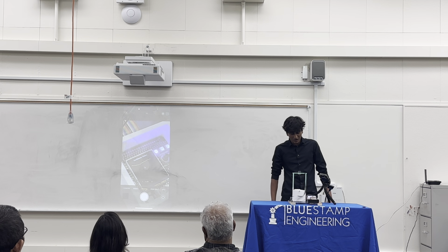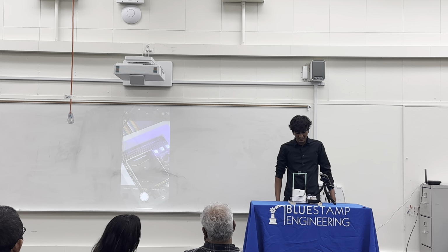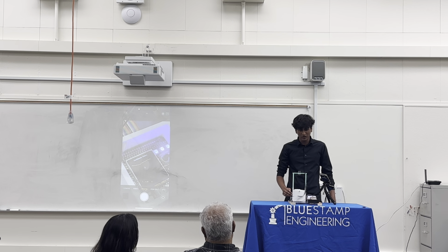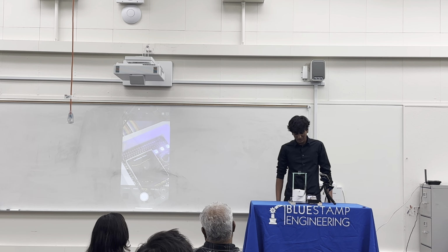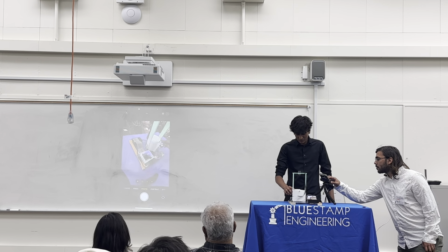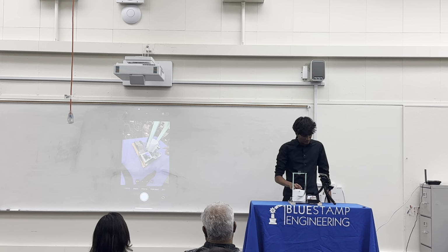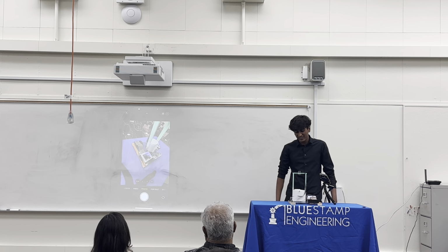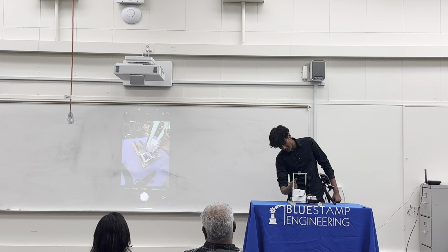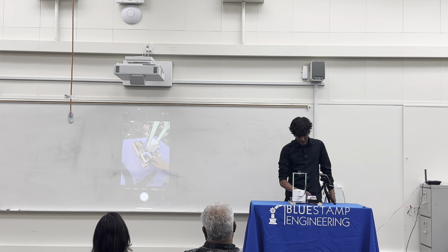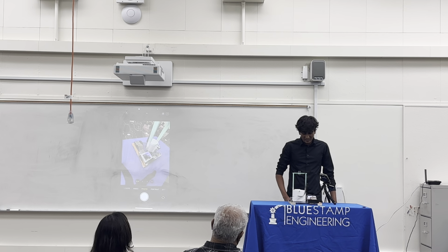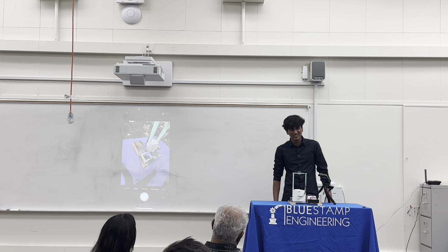And yeah. Throughout this project, I learned a lot of different things, but I'm just going to quickly give a technical overview of all the components. This main part was completely CAD'd and 3D printed. It's the coin sorter function, and it has a hole through here that has an axle. On the back, you should be able to see through there, there's a little servo, and it turns based on what the camera up here detects. Over here, I have my display, my joystick, and my LEDs. And this is my Raspberry Pi, and it has a script running on it that contains my trained model. That's essentially all of the technical stuff with my project.